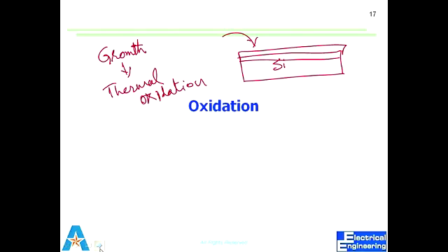Anyway, you'll do one layer of devices. We'll look at a very, very fundamental process, oxidation. I could have put photolithography before oxidation, but oxide is something that we can grow on a bare wafer. For lithography, first we have to have some material that we want to use as a hard mask later on. So oxidation comes probably before lithography. So let's start with oxidation.